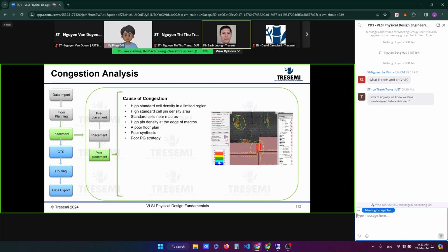For example, if historically for that particular type of design and technology you can route at 70%, then that's the target. But if you come in at 80%, then you're too high, and you have to back out and grow it to where the floor plan is 70% utilization or density. The other way around, if you come in at 50%, then you are too big, and you shrink it to around 70.